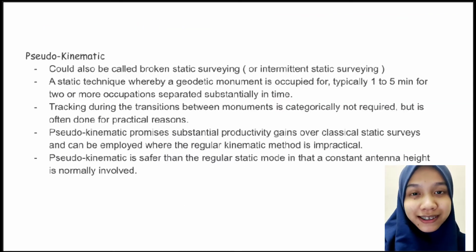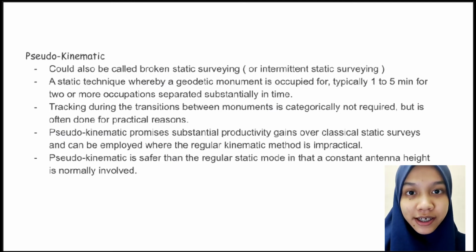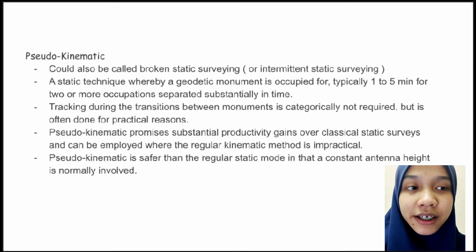Next, we will talk about the Rapid Static GPS. This GPS uses the techniques of the geodetic monuments. Typically, from 1 to 5 minutes, 2 or 4 occupations will receive data, but at separate times. It is also safer if the constant height of antenna is involved.